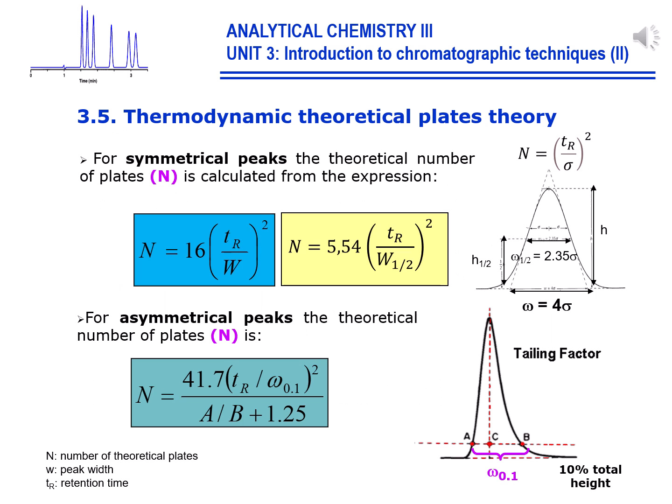Peaks eluting from a chromatographic column can have a Gaussian distribution. This is to be completely symmetrical. In this case, N is defined in terms of the peak distribution as shown in the upper formula. The width at the baseline for a Gaussian peak is equal to 4 sigma.